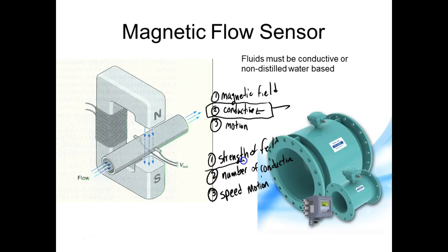So if I have control of this, then I know the material that's flowing through here, then I can calibrate this. So if I can calibrate, and notice this is an electromagnet. What advantage does the electromagnet have over a regular magnet? Over a permanent magnet, yeah, we can turn it on and off, or we can control its strength, right? So between the two, we should be able to calibrate this thing. If I can measure the flow of material somehow, then I can calibrate.